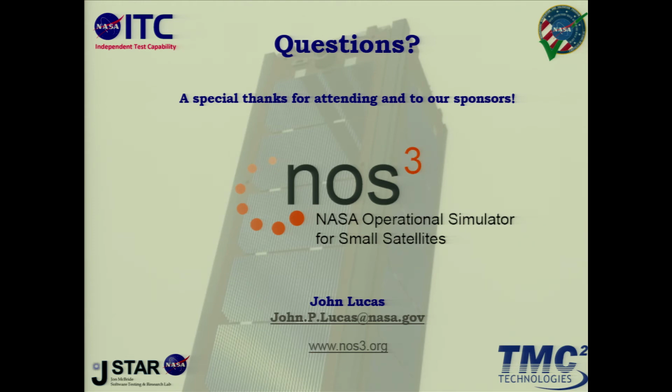You have a question? Could you just say what your store and forward radio is that you mentioned in passing? We're utilizing what was the L3 Cadet UHF radio. It has now been taken over by SDL, the Software Dynamics Laboratory. They are soon to make another batch of them, I believe, but it is UHF band, basically for Wallops. And so us and a few other Goddard Space Flight Center missions are flying the same radio in order to communicate with Wallops. Store and forward means what protocol? Store and forward is essentially, it's got 4 gigabytes, I think, of storage on the radio, and so we're basically pushing data to it until it finally gets a ping from Wallops, and then it will shoot it all down at once at 5 megabits per second.